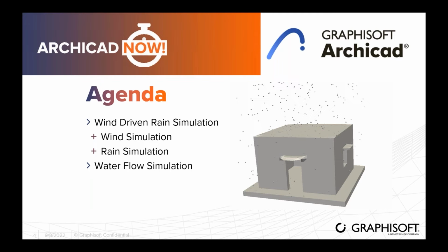So we are going to do two different simulations. The first is wind simulation. We need to set the wind data around the building, and then we are going to perform the rain simulation over the wind simulation results. So it's two simulations, and we are going to combine the two, and based on the first one, we are going to do the rain simulation after that. And then we will also see the water flow simulation. Basically, once the wind falls on the building, the water will flow, right? So that simulation is the water flow simulation.